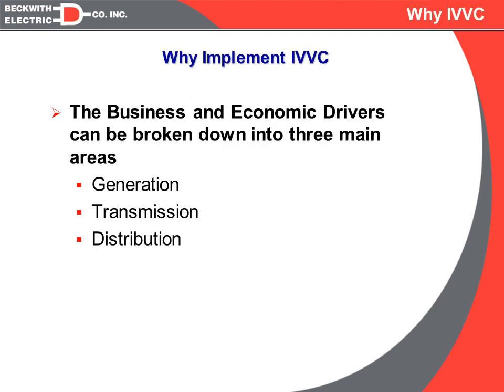So, again, and we covered this in the introduction a little bit, IVVC is Integrated Volt-VAR Control, and the goal is to control the distribution voltage in a coordinated manner using a combination of regulator and LTC, load tap changer transformers, along with switched capacitor banks downstream.